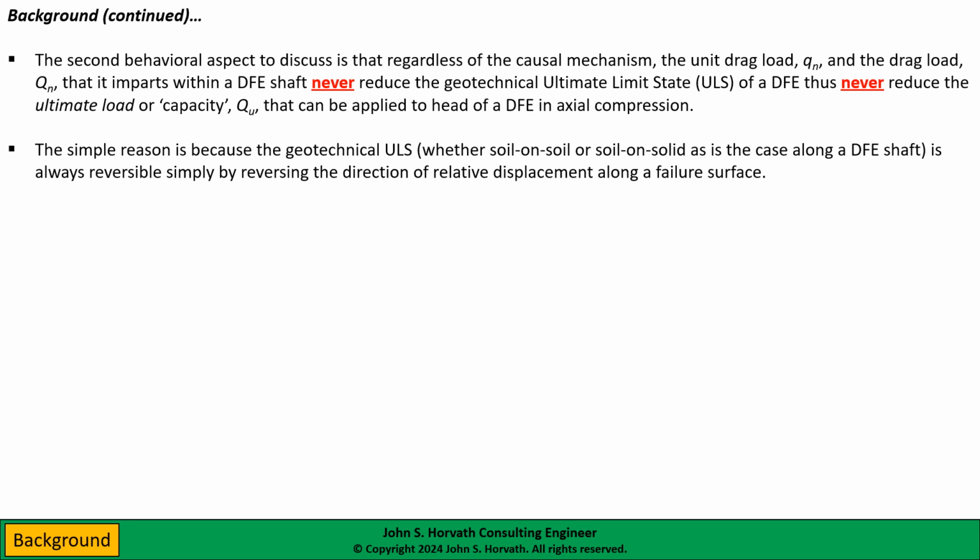In fact, if you think about it, that's what occurs when you drive a pile in the ground. You fail it continuously as it goes into the ground. And the reason I'm emphasizing this is this single fact is where the understanding of residual loads especially has come into play over the last 50 years.